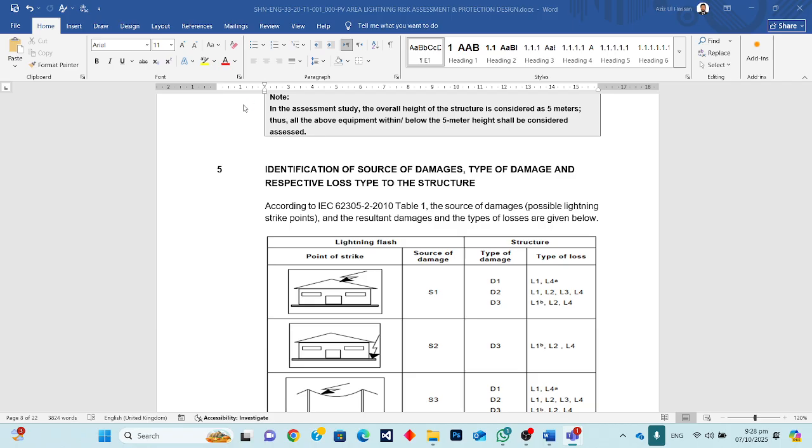And also, we will see in the next calculation the lightning strike per area, in that area where we are performing the assessment. We have to consider the hill area and the other options where we are installing our solar power plant. In the area I have considered, it is a mining area, and the client has leveled the ground.